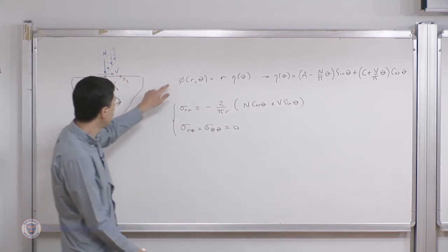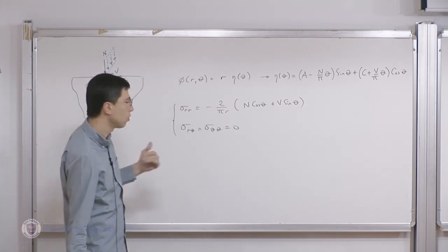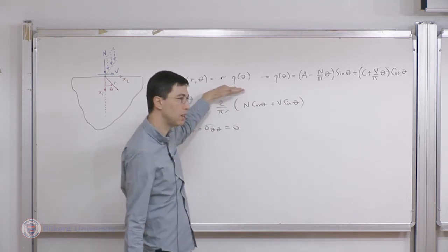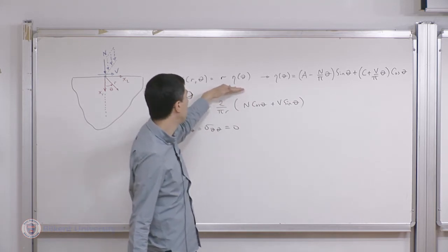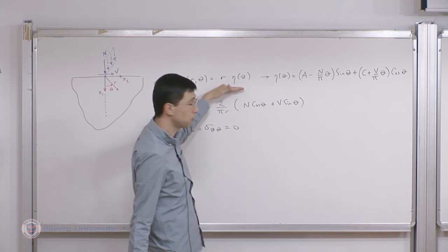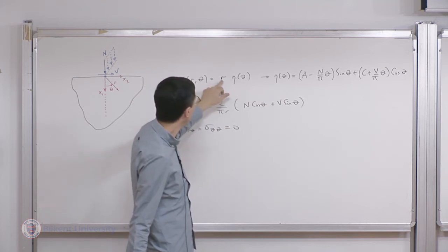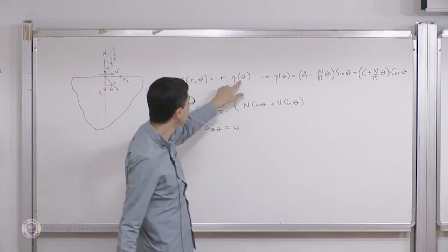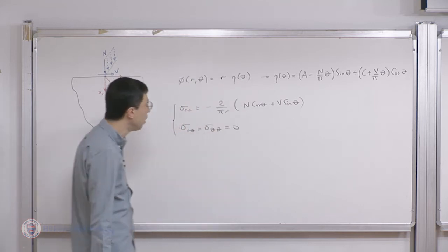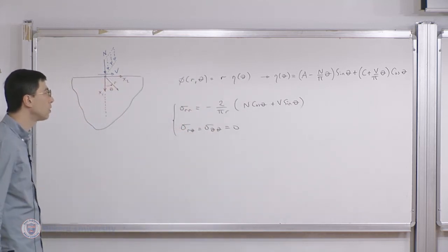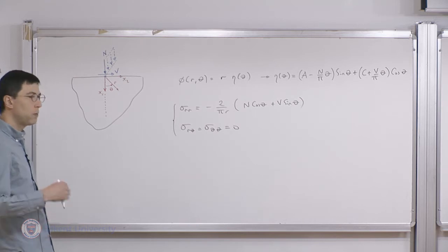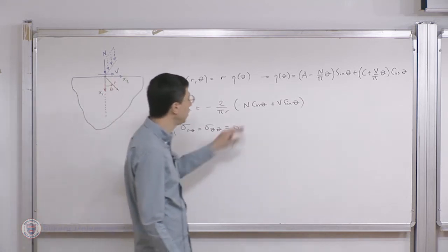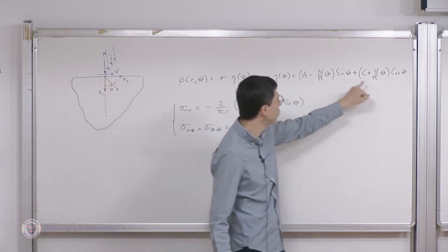Okay, so then we sought what the Airy stress function was. We proposed a problem-tailored form, and we first said, well, okay, let's say that a separation of variables approach is applicable. Then we argued that for equilibrium to be meaningful, the r dependence must be linear, and then there's another function, eta of theta. That function is general, so we didn't know what it was from the outset. Then we imposed compatibility, and we found a general form for eta, where these were initially constants.